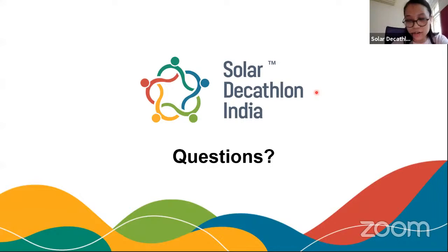Another thing is that in your SLMs in passive design module, you might have seen we talk about radiation received on each direction, how radiation received is different for each direction. So based on that, you can come up with various WWR for different directions so that you minimize the radiation received by your building. Could I also add, Amanda, that there will be some effect of self-shading within the building. So you may have to watch for that.